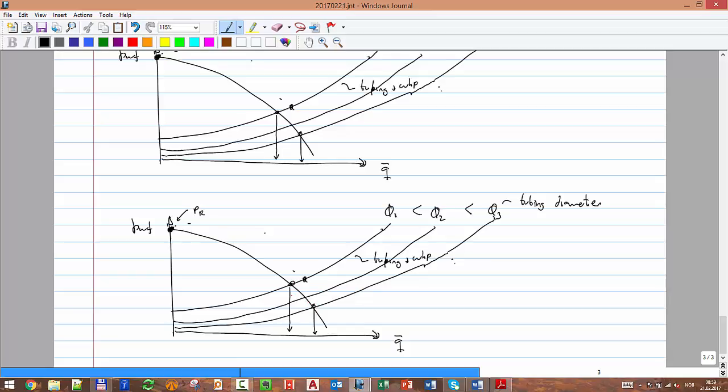changing the tubing. Okay, another thing might be that the tubing in that condition you checked and there is some scale on the tubing. Okay, scale is like inorganic salt that deposits in the walls and comes from water, okay, from all of these minerals in the water, and is with time accumulating and making the flow area smaller and smaller and smaller. So what you can suggest to your boss is say, okay, I will come with a tool, with a reamer that will take away all the scale in the walls and then increase the size of the tubing, increase the diameter of the tubing.